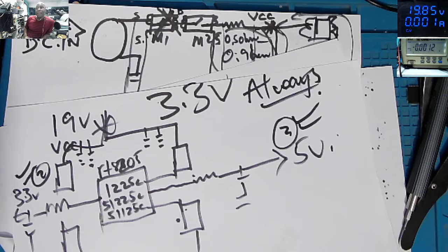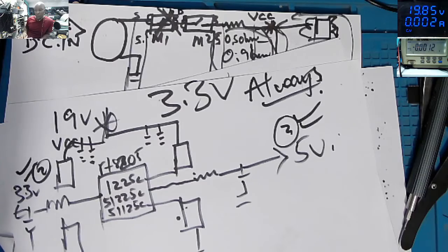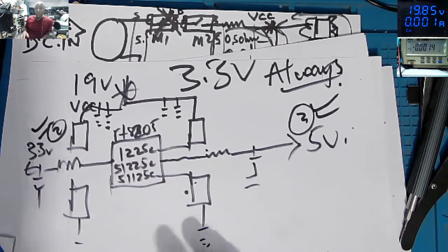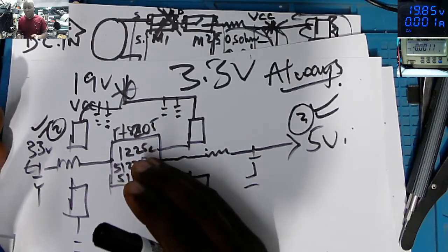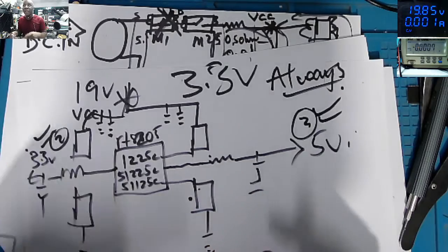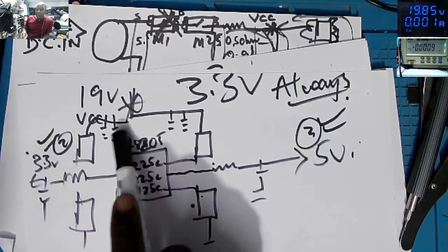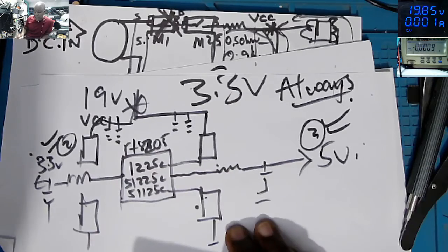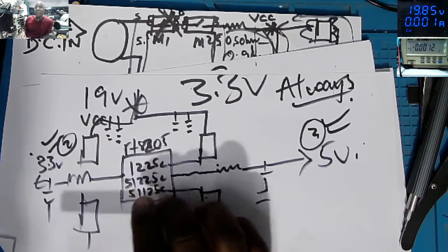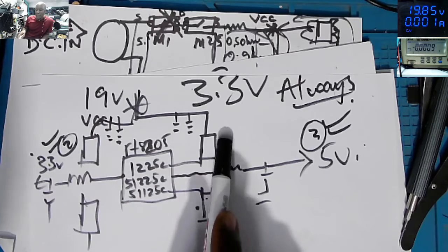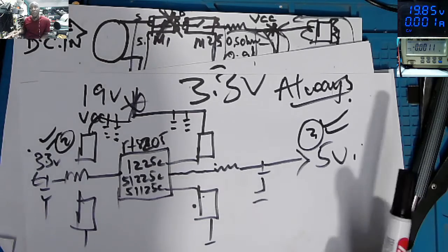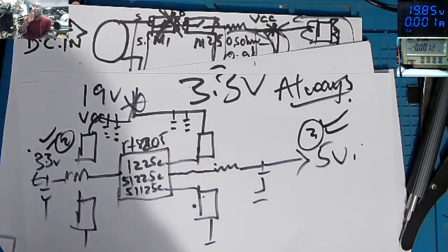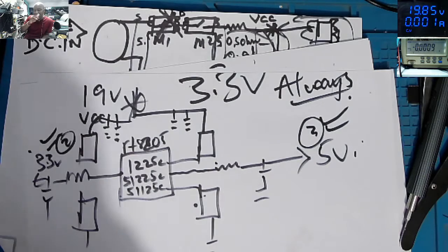And bad things can happen on this power supply. So that's how motherboards work, from the 19 volts to the power supplies. If you check every power supply, you have two MOSFETs, ceramic capacitors to prevent the spikes, and the driver, the regulator of the power supply, which is inputting high voltage, which is 19, and outputting lower voltage, either 5 volts or 3.3 or 1 volt for the processor or for the GPU.